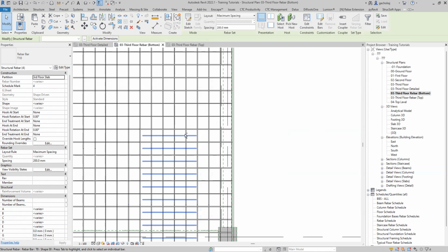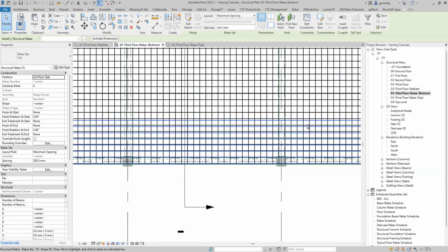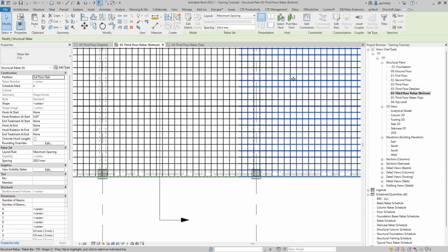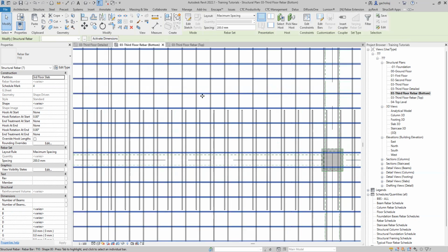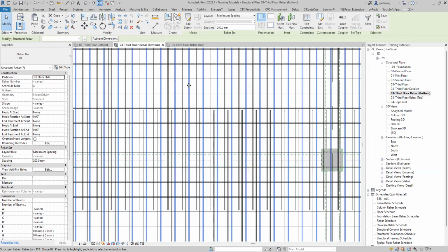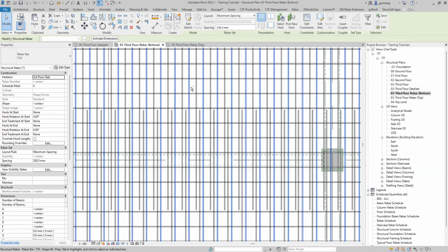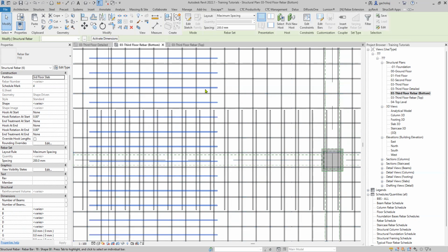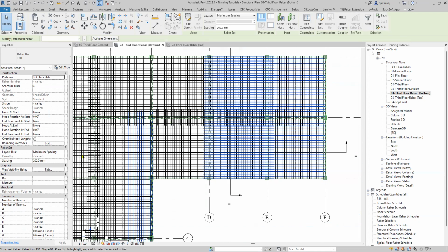It might be a bit tricky, but just hover your mouse over the bottom ones and select all of them. If you select bottom 2s by mistake, press Shift and then use the minus key to remove it. Then press Control again and continue adding your bottom ones.